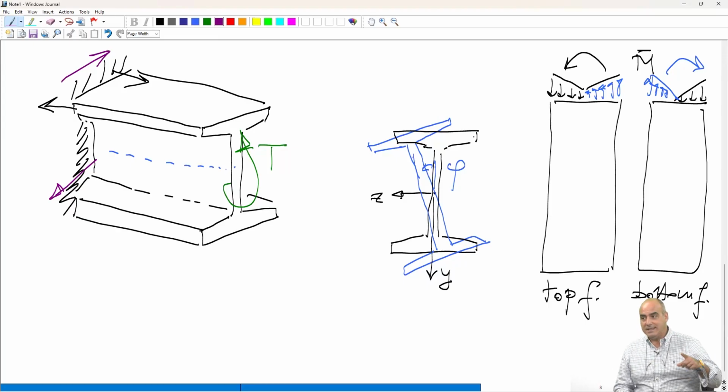The shear forces are the result of the parasite bending moment, which is non-uniform along the axis of the beam. But those shear forces have a lever arm because they are not applied at the same level. They are applied in the two flanges. And you see that they form a torsion moment which is resisting the applied one, together with the usual blockage of the rotation.